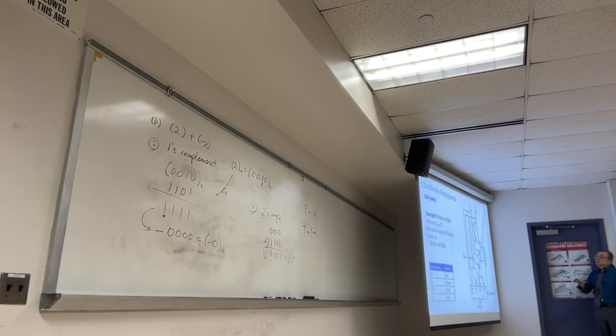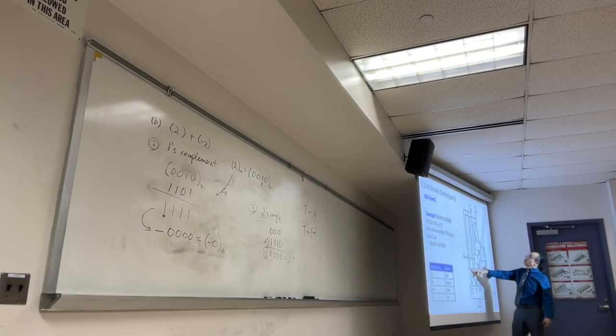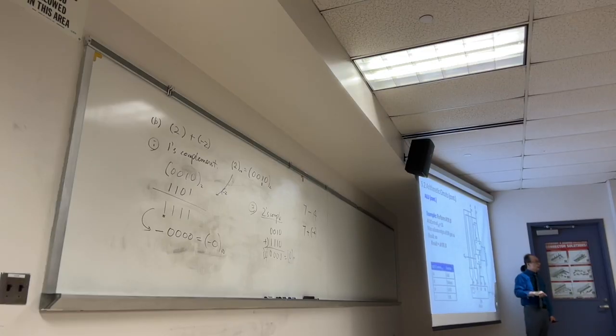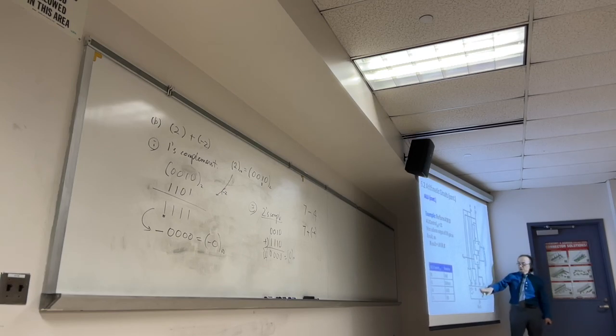So here's a quick example, A or B. For the OR, let's just put A or B. So in this mux, you just need to select 1, this input, and then the output is going to be ORing it, right? And all of this, there is calculation waiting here. However, we don't select this as an output.